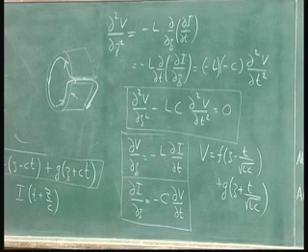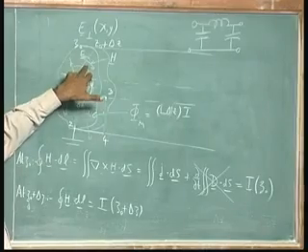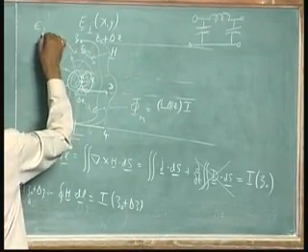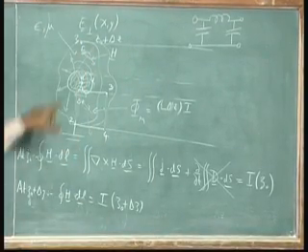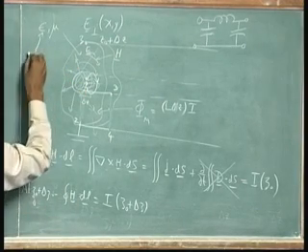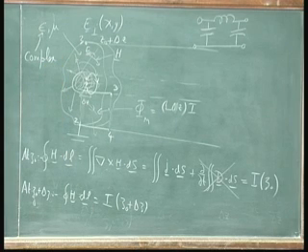Now of course, any real transmission line is not ideal. So where are the non-idealities of a transmission line? One non-ideality you have is that this medium, which is characterized by epsilon and mu, may be lossy. So epsilon may be complex. If epsilon is complex, we know that you will start having a leakage current.